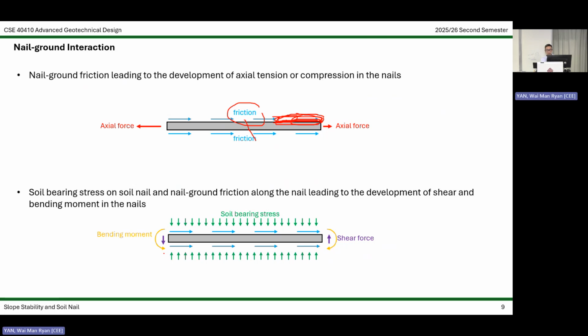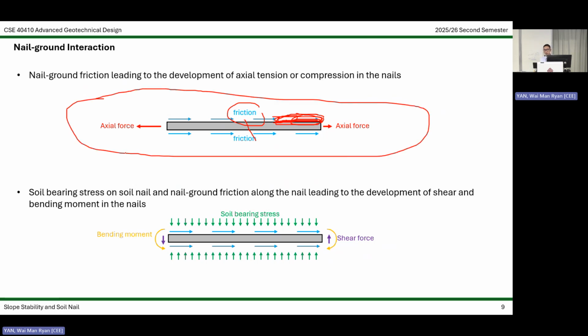But since a nail is a rather strong material, normally we don't need to consider bending and shear force effects because they are very small. We do not expect the nails to bend a lot. The nail should be used primarily based on its axial force, the tensile force.